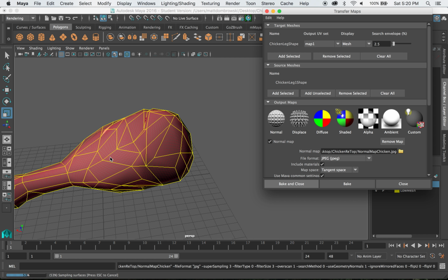You can always go back and do this method on all the different pieces to achieve a detailed result. And as you can see, with Maya's shrink wrap tool and the quad draw tool, this works really, really well. Back in the day, we actually had to go back and rebuild it with extruding and all that. Now we can actually just wrap shapes around our characters, which is really nice.